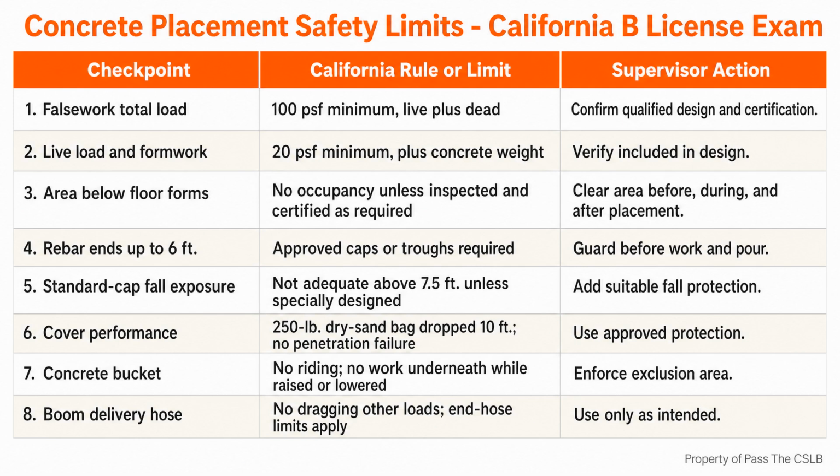For boom pump operations, the delivery hose cannot be used to drag other loads. The same safety orders state that a boom delivery hose is not to be used as an end hose, except for shotcrete or when it is supported by the walking surface. These restrictions keep the placing system used for its intended function, rather than turning the boom and hose into general lifting or dragging equipment. The report also identifies a prohibition on adjusting single-post shores to raise the formwork after concrete placement has begun. That is another reason I want elevations, line, support, and certification settled before the first discharge. Wet concrete is not the time to redesign the support system through field adjustment.